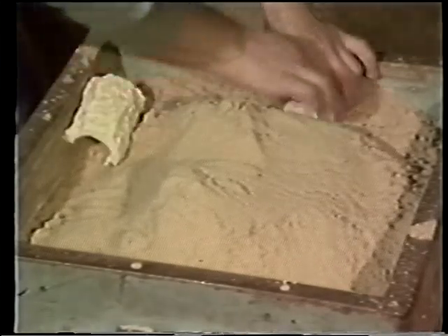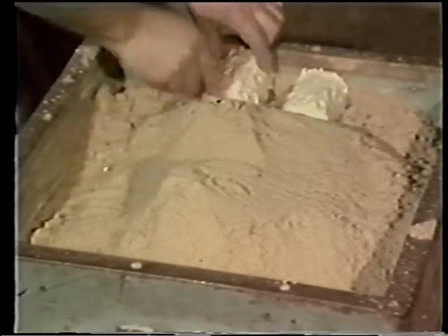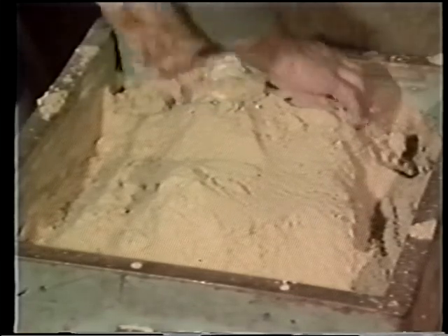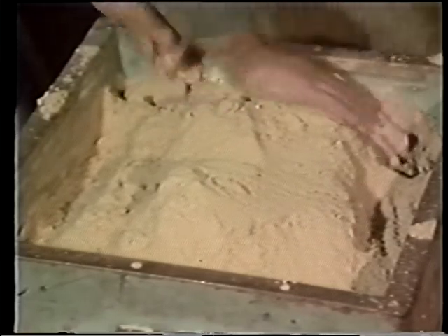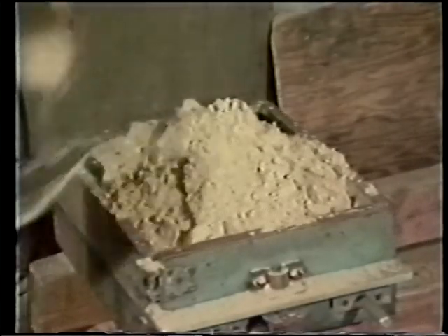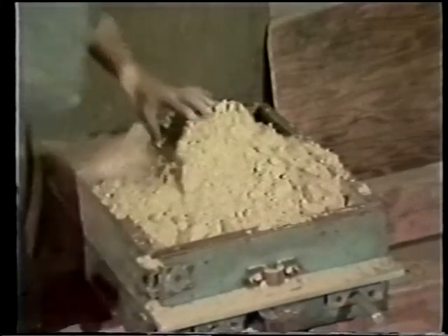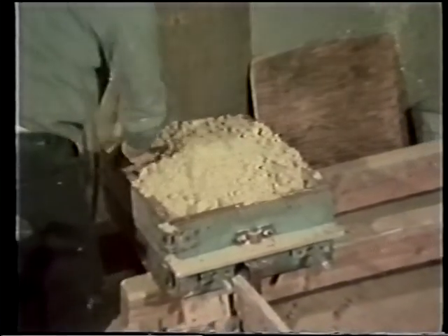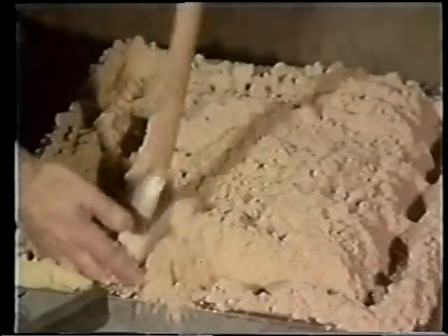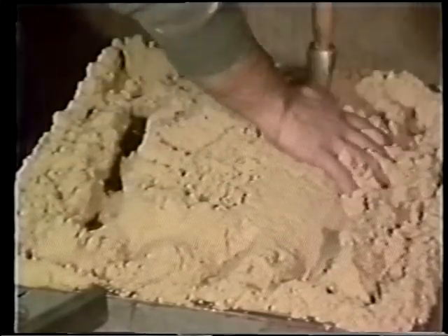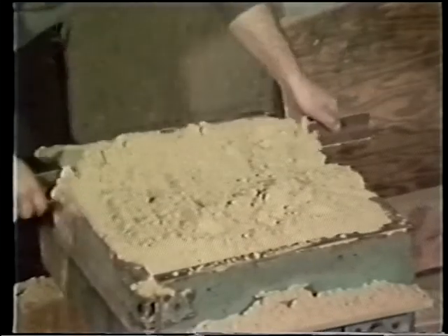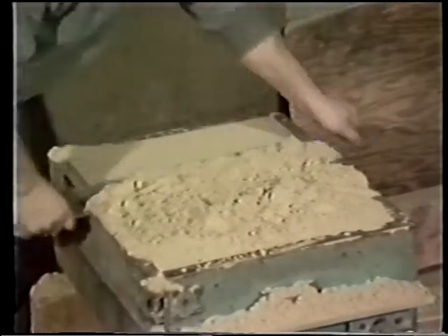Special asbestos sleeves insulate sprues to prevent the sprue metal from solidifying before the metal forming the part solidifies. This reduces shrinkage defects. Additional sand is shoveled in to fill the mold and back up the initial molding material. The sand is packed down firmly to assure that all areas are filled. Excess sand is then removed and a smooth, level surface is produced.